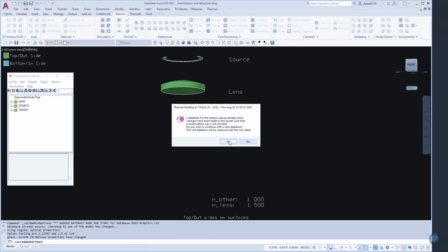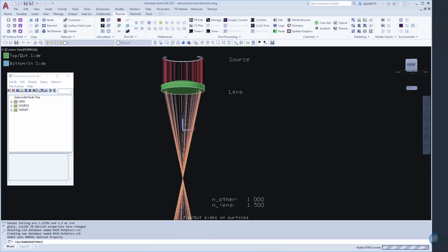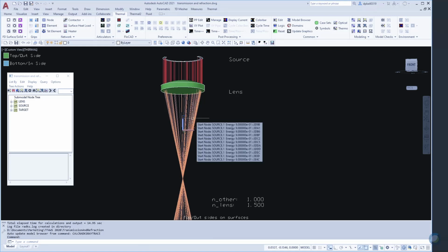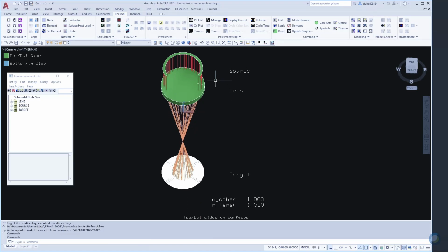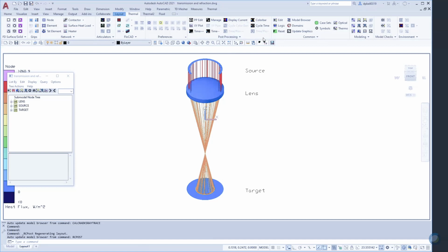So if I run this calculation, calculate radks with ray tracing, and I've set it up to just shoot from my source and then figure out how much is reaching the other side. But you can see that the color changes. Red would be at full level, and green or orange means it's been reduced because we should be at 90% of our original radiation.